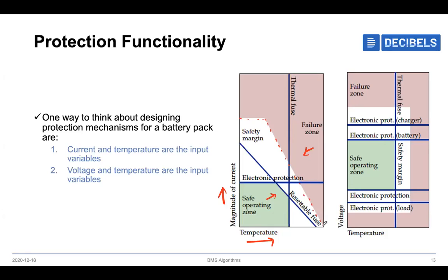But when we are developing protection logics, we should not go directly with the value defined by the manufacturer. We have to restrict ourselves to some safety margin, which we keep over here. We can move up to here, but this will happen only when this protection and this protection fail. Here I am giving two degrees of protection: one is thermal protection and the other is current protection.